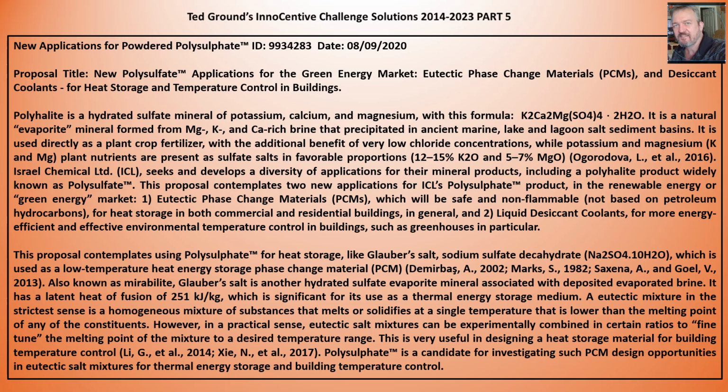So I'm thinking that maybe the polysulfate material could be used or experimented with as a eutectic mixture in order to be experimentally combined in certain ratios to fine-tune the melting point of the mixture so that there's a desired temperature range where it absorbs and releases heat as a heat storage material for building temperature control.